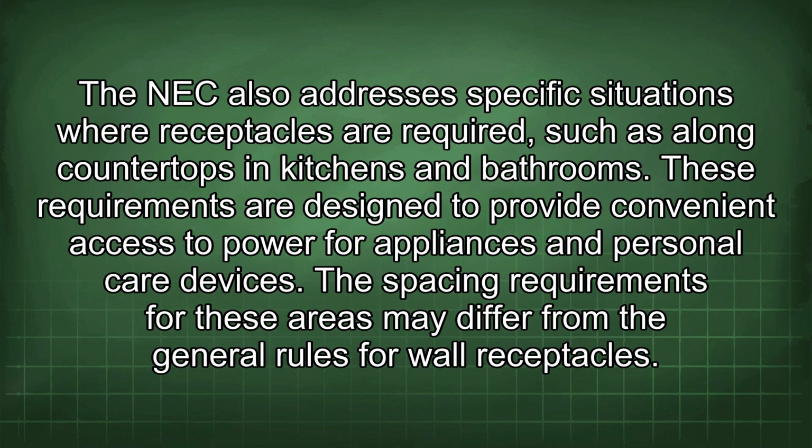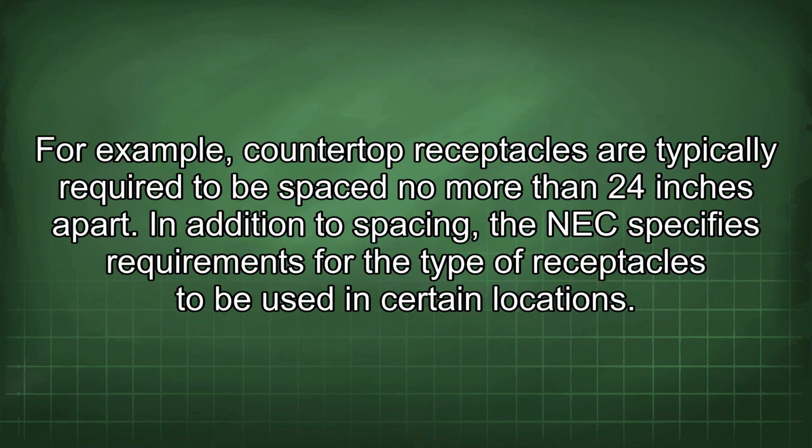The NEC also addresses specific situations where receptacles are required, such as along countertops in kitchens and bathrooms. These requirements are designed to provide convenient access to power for appliances and personal care devices. The spacing requirements for these areas may differ from the general rules for wall receptacles. For example, countertop receptacles are typically required to be spaced no more than 24 inches apart. In addition to spacing, the NEC specifies requirements for the type of receptacles to be used in certain locations.